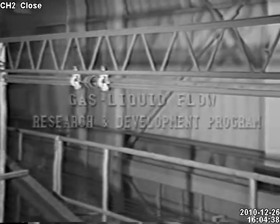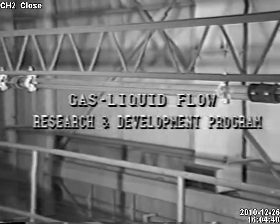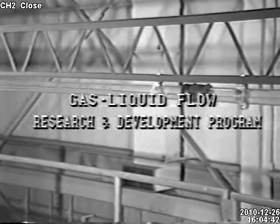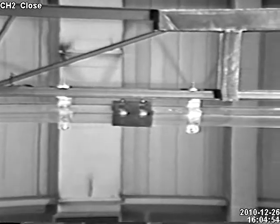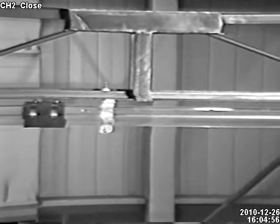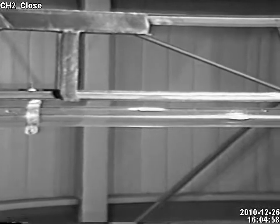Two-phase pipeline flow can lead to excessive pressure drop and hence loss in capacity. Pressure drop in gas-liquid flow is complicated by the variety of flow regimes which can exist. Current work in the Transportation Research and Engineering Department is aimed at developing better designs by better understanding of these flow regimes. This film will show these flow patterns and the effects of pipe inclination and flow rates.